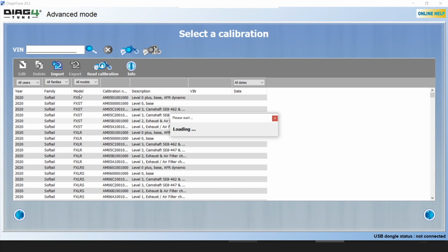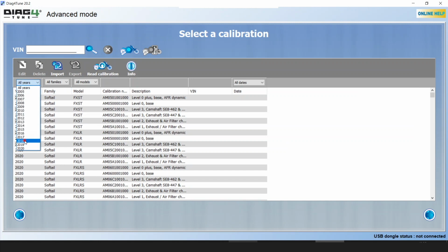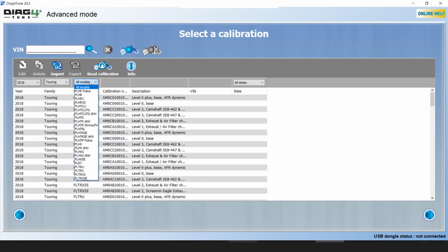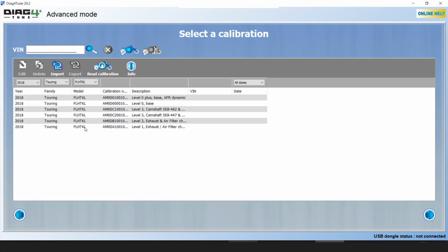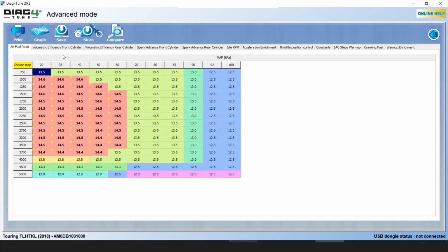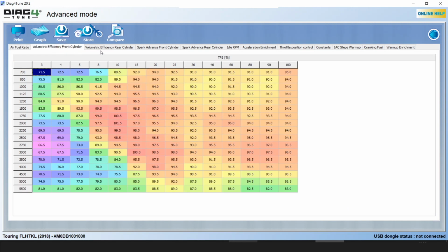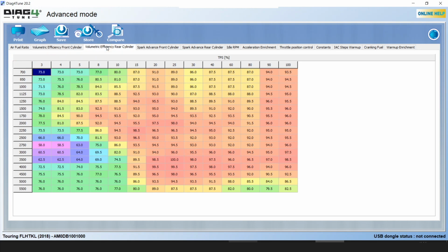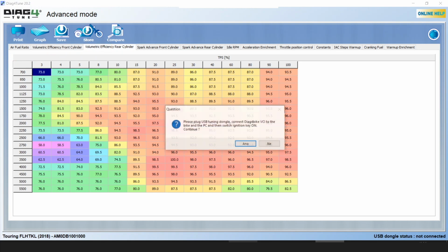The goal is to remedy the situation and set the VE maps in the control unit so that they correspond to the real configuration of the newly installed components in the motorcycle. Setting correct VE maps brings the engine's behavior back in order and eliminates the majority of the problems that began once the new modifications were made. The emissions behavior of the engine also turns back to optimal levels. The end result is a comfortable, stable motorcycle that you can make full use of the newly installed accessories while maintaining low emissions.